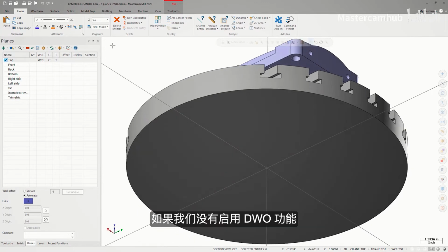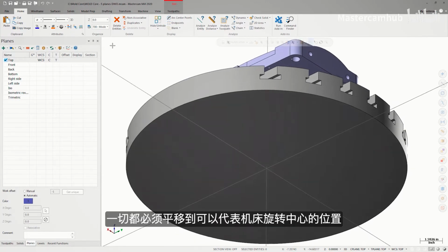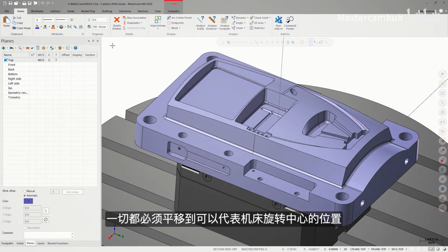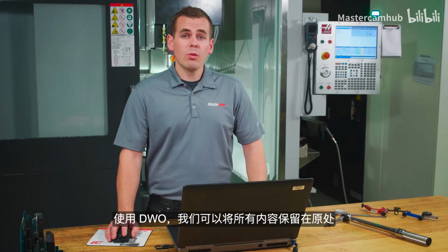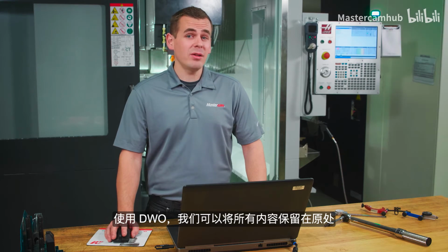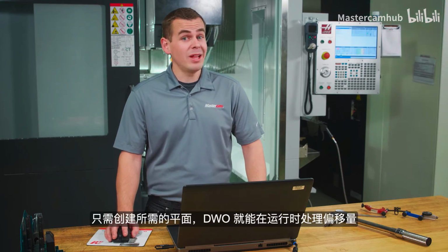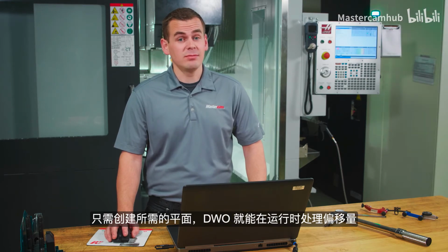If we didn't have DWO available, everything would have to be translated to a location that correctly represented the center of rotation on the machine. With DWO, we can leave everything where it is and simply create the planes that are needed, and DWO will handle the offsets at runtime.